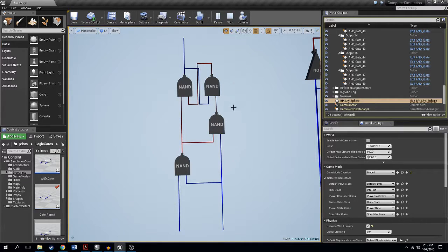So right away when I start the circuit, we see that it takes on basically what we would expect. Both of our inputs are off, so our output for this bottom left NAND gate is on. This NAND gate still has one input that's off, so it's on. And then this little feedback loop ends up evaluating to where our top right is on and our top left is off. And this right here is our output, and these are 2 inputs. This bottom left input is normally considered the actual input, and the bottom right is normally called the setter. And we will see why it's called the setter here in a second.